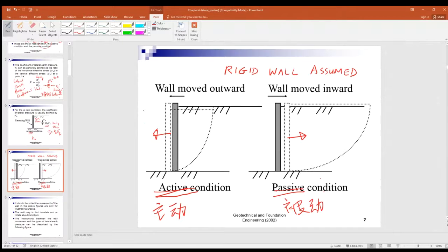Now, in excavation, suppose we are going to do some excavation here, say to construct a basement. If we construct this wall, what will happen? Because the wall is moving out, the soil will go out too, right? So the soil will be lost here, and there will be subsidence or settlement in the ground surface.